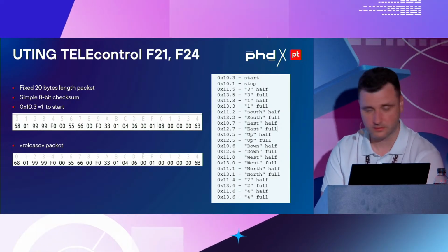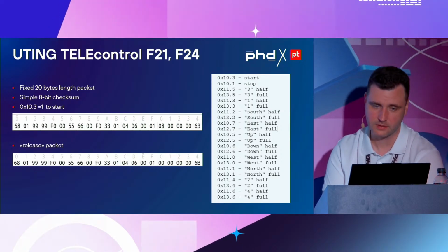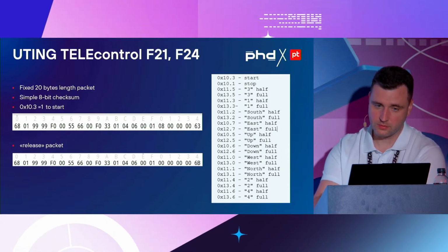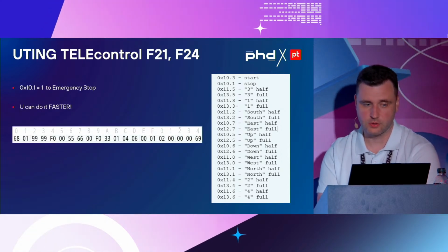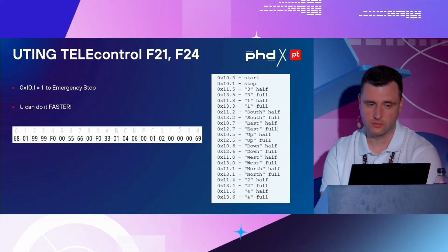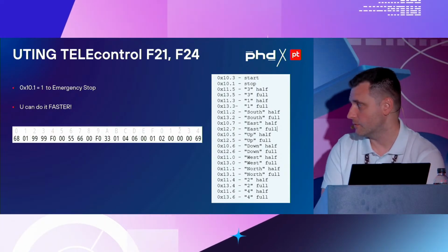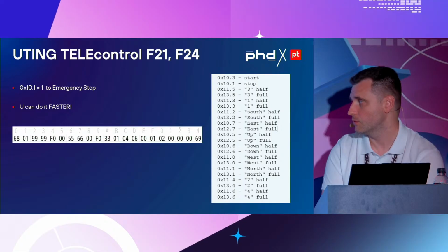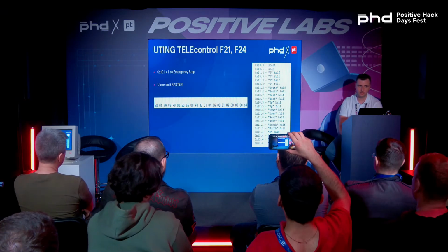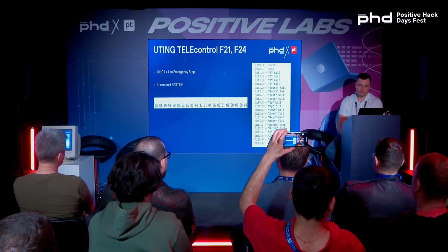Each button is just bit-based, coded with its own bit, and it requires either a full pressing or half of the pressure. The emergency stop button and the reed switch are the same thing for that system. By sending such a packet, you can simulate pushing the emergency stop, and the signal from the original remote control will never be received.